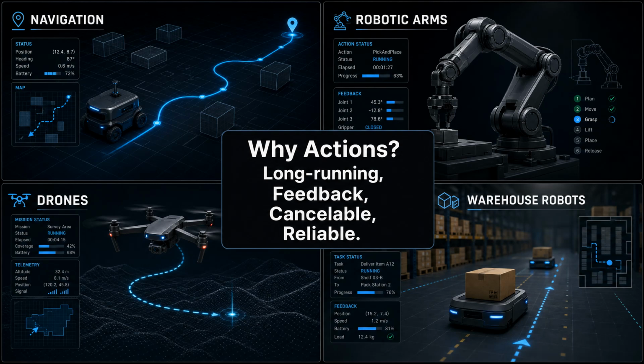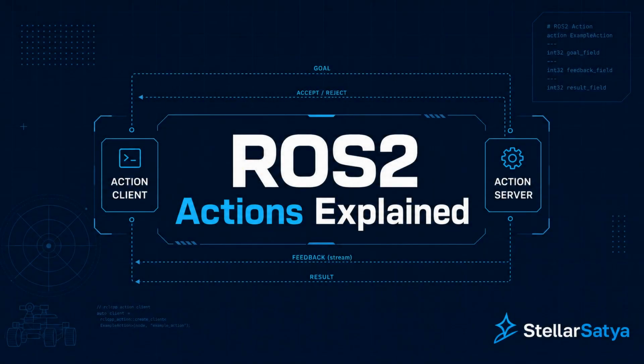Let's quickly summarize what we've learned. ROS2 actions are designed for long running tasks. They provide three important capabilities: goal, feedback, and result. Unlike services, actions allow us to monitor progress while a task is running. They also support task cancellation when required. Whenever your robot needs visibility into a long operation, actions are usually the right choice.